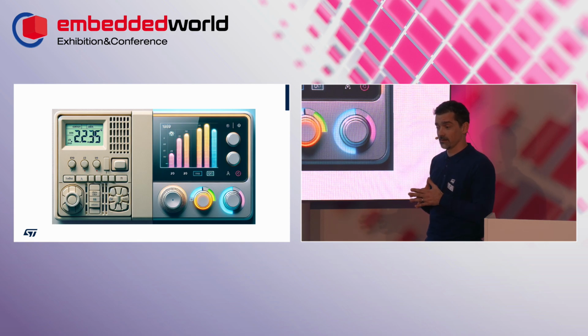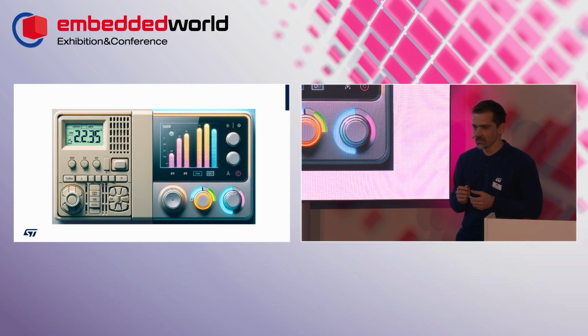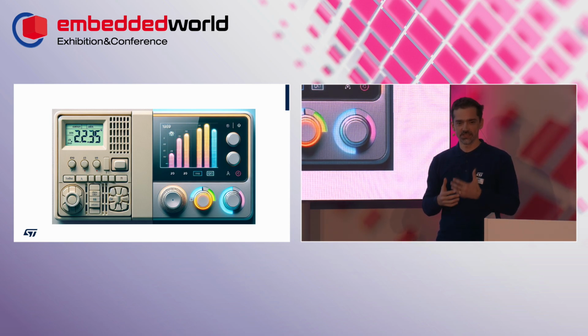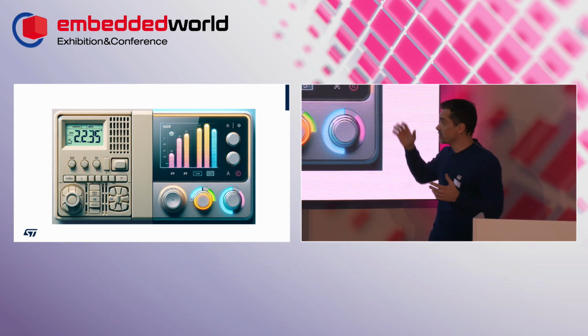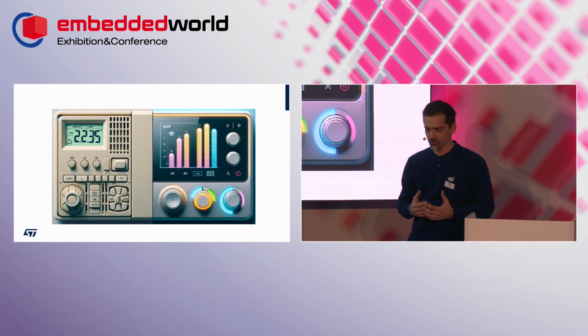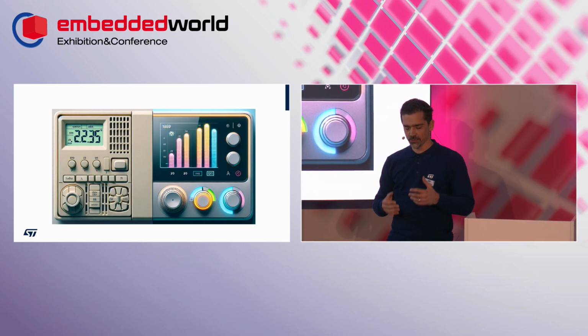But I was talking about microcontroller-based products. And microcontrollers are not designed to do this heavy task that is updating a user interface. Updating a user interface means a lot of pixel processing. It's a lot of heavy computation. Depending on the size of your display, the more pixels you have on the display, the higher the definition, the more expensive it is in terms of processing.